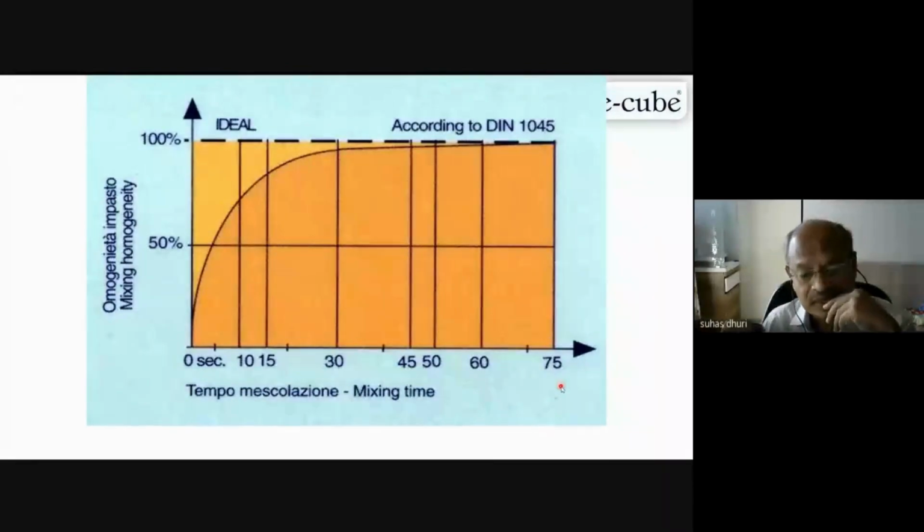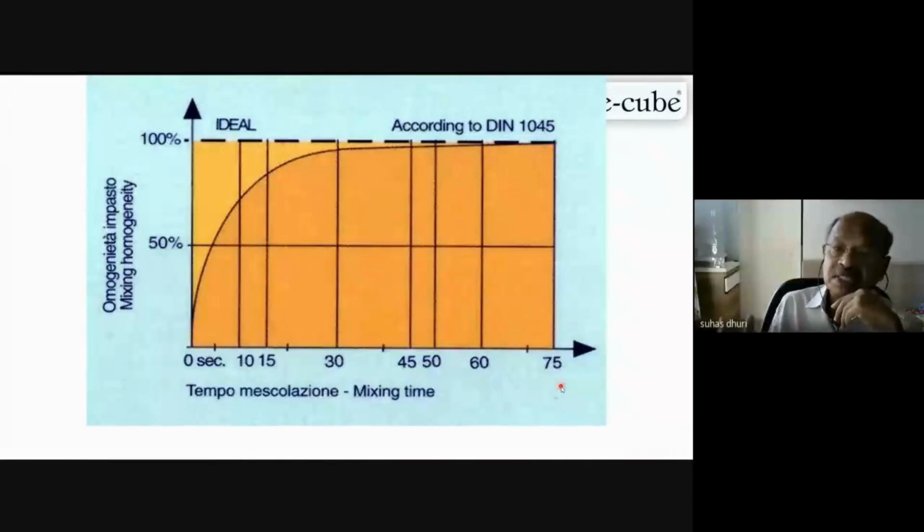That is okay, if you add water, definitely flow is more. But if the mixing time is low and the dispersion of admixture is not proper, then whenever we are in transit, the mixing happens and dispersion takes place, and we'll find the flow has increased. So that is also possible.